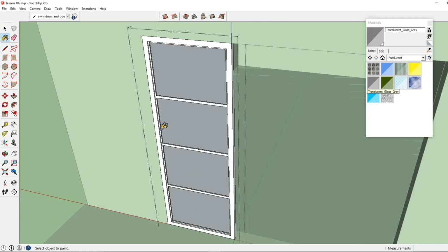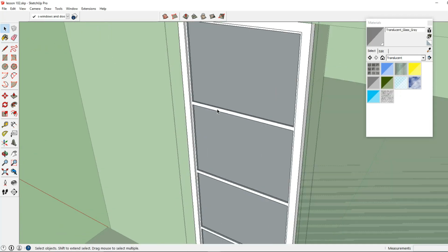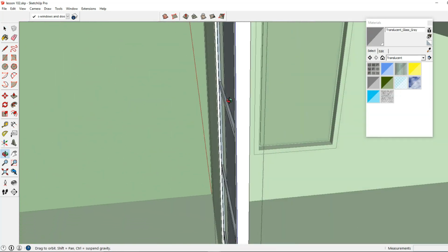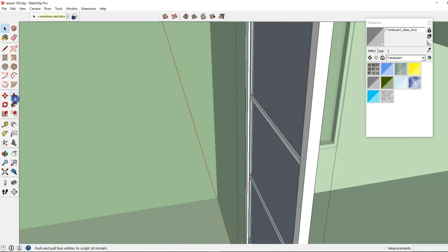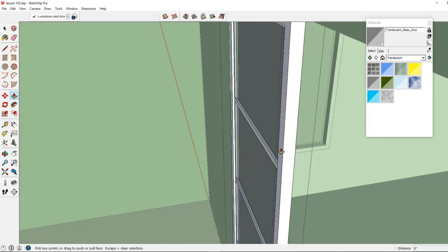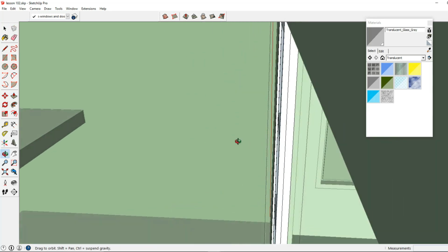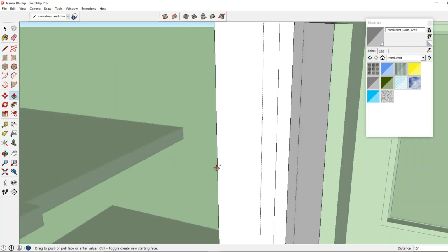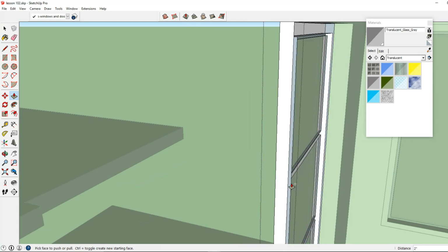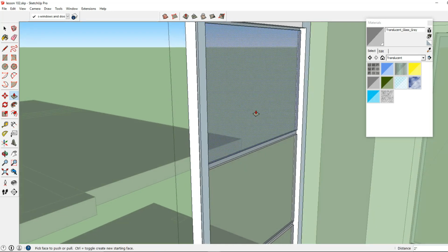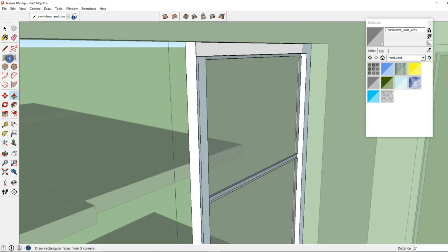Oops, let's back up. And now I don't really see it breaking through, so I have a surface here that I didn't pull all the way through. So let's grab this and let's drag this along here. You may have to toggle your Control or Command key to make sure that it's pulling through, and let's go ahead and click that, and there it just automatically cleaned that up.